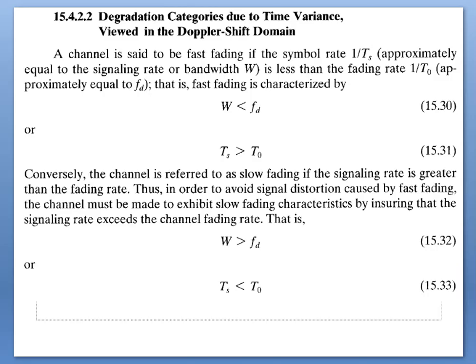Ideally, coherent demodulation that locks on to and tracks the information signal should suppress the effect of FM noise and thus cancel the impact of Doppler shift. However, for large values of fD, carrier recovery is difficult to implement because very wideband phase-locked loops need to be designed. For voice grade applications, the bit error rate is approximately 10 to the power of minus 3 to 10 to the power of minus 4.